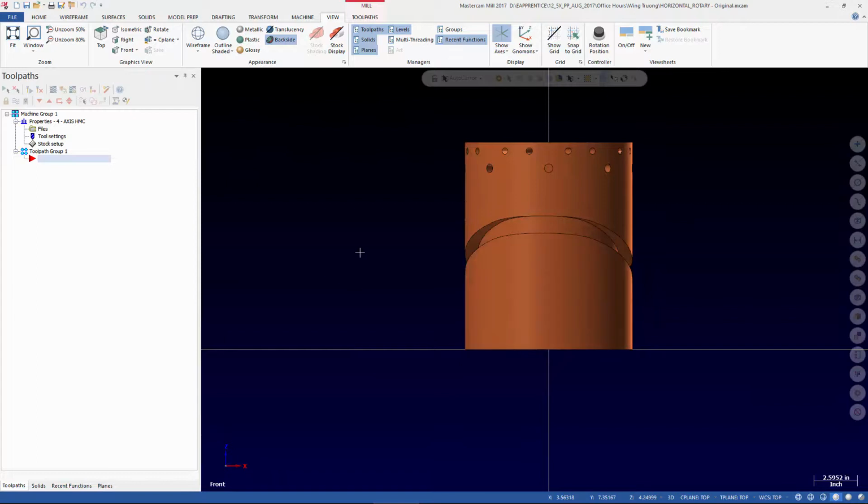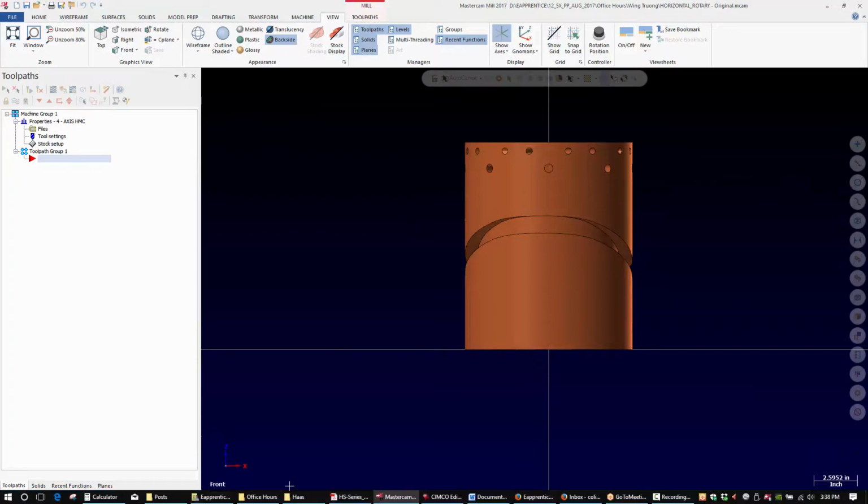A lot of people don't realize that the generic Fanuc posts will support 4-axis rotation and 4-axis multi-axis motion out of the box. So to do the multi-axis path, you still need the multi-axis license, but we can still drive that with the regular 4-axis post. There is logic that exists in that post.